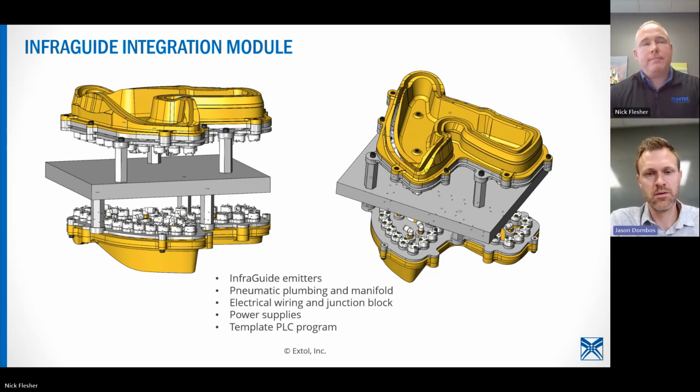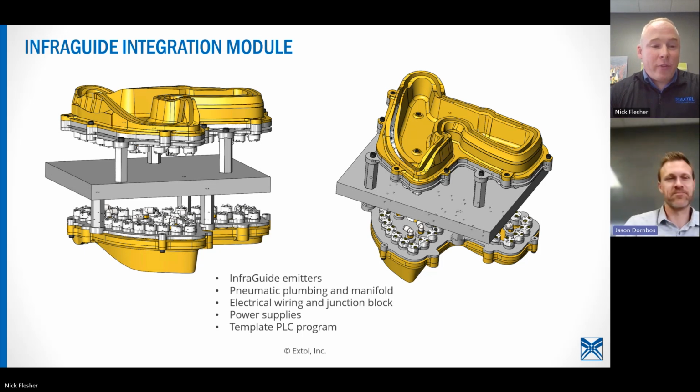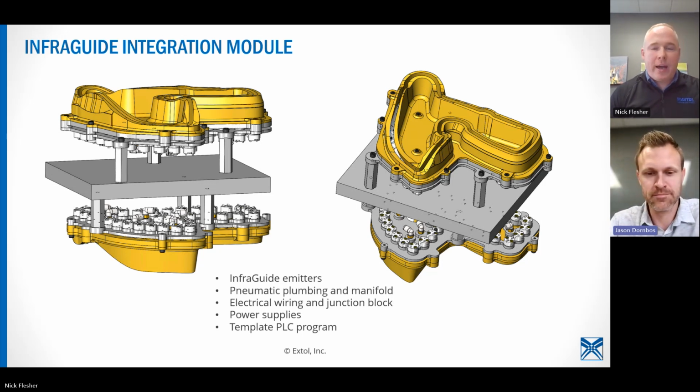Nick, Jason? Are those just a mask? They're not a mask. InfraGuide is guiding the energy. It's guiding the infrared energy. We put it in the name kind of on purpose. InfraWelding has had some challenges with respect to masks. Over the years, we've heard that masks can be less effective than what is required. You can kind of heat more of the parts than you need to. These have a very defined cool part and melt part. So, very focused energy is what you're going to get with it.